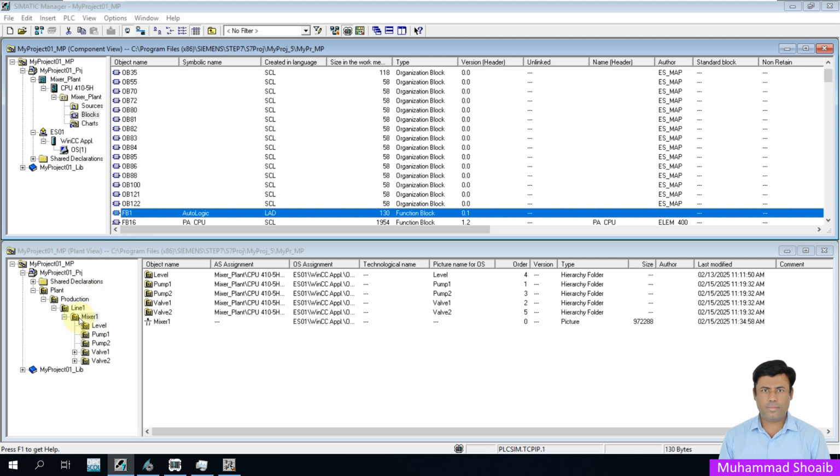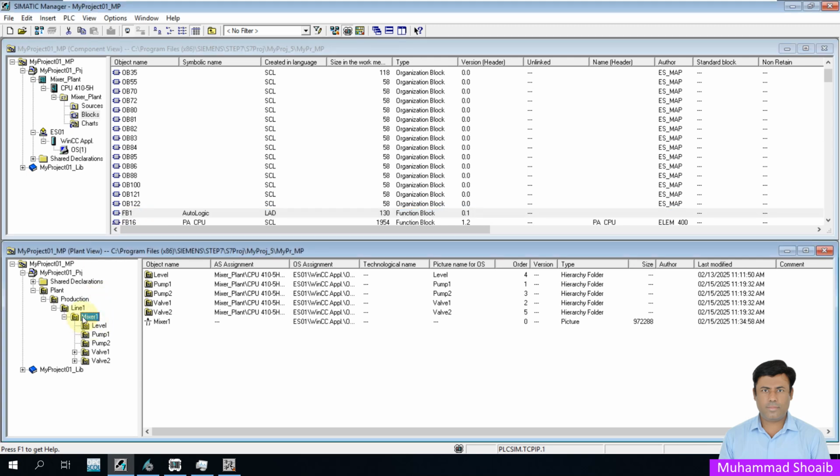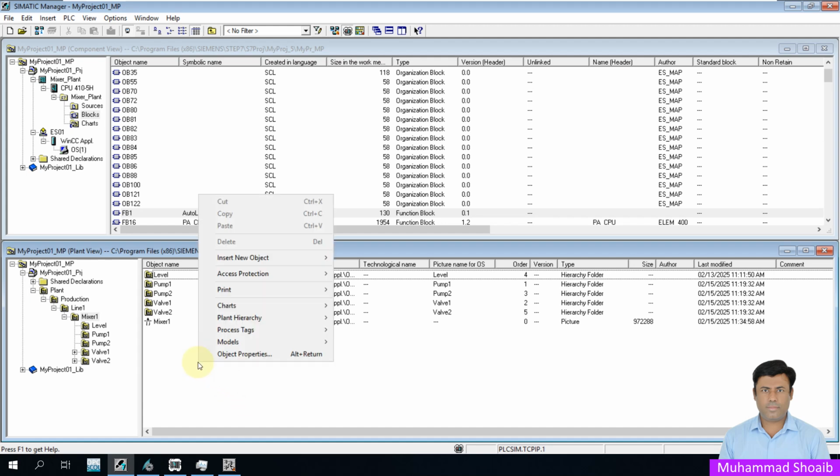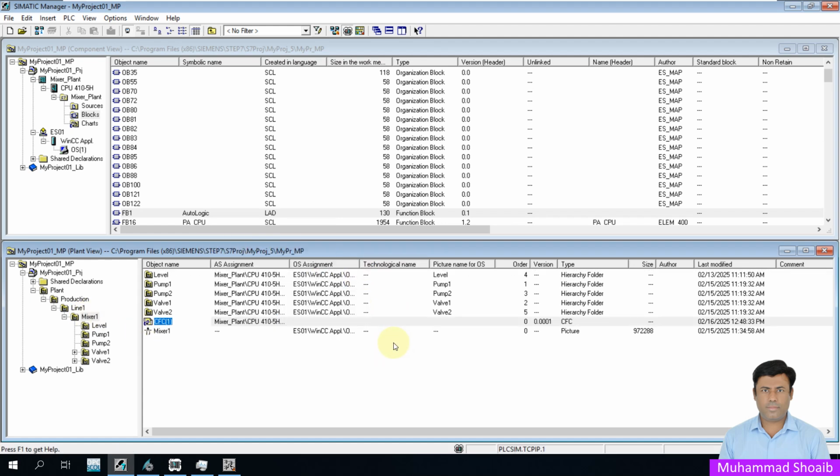Okay. Now come here in the mixer and then right click here, open the mixer, right click and insert a new CFC chart and put the name of the chart.